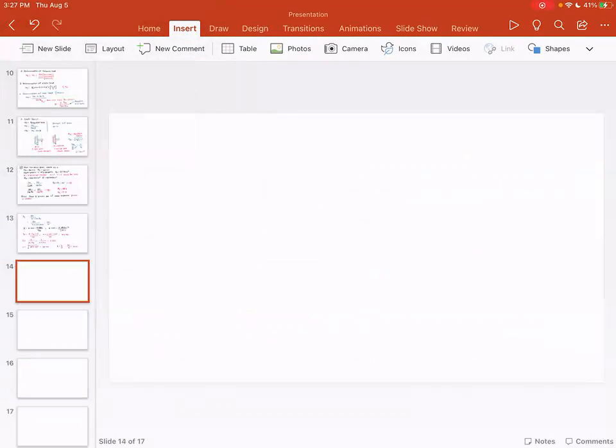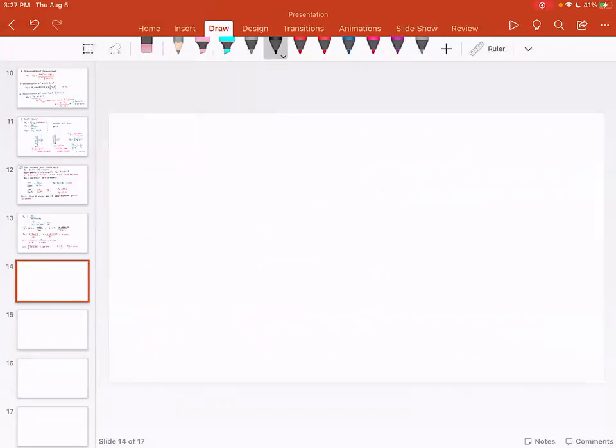So the next step is determination of torque. Torque is equal to power times 60 divided by 2 pi n. So power is in watts, 2750 times 60 divided by 2 times pi times n, where n is 1100. That gives me 23.8 newton meters.